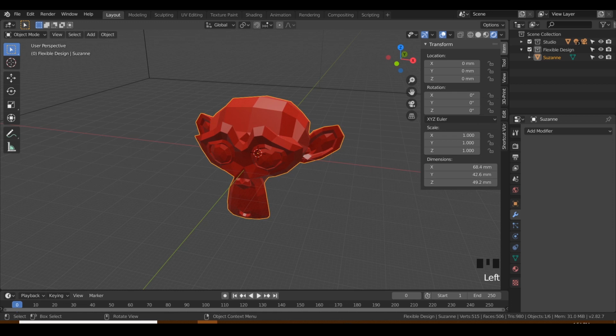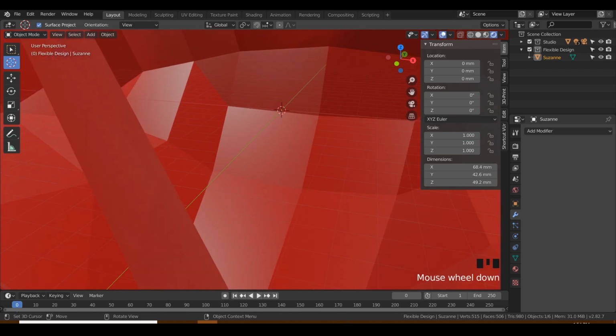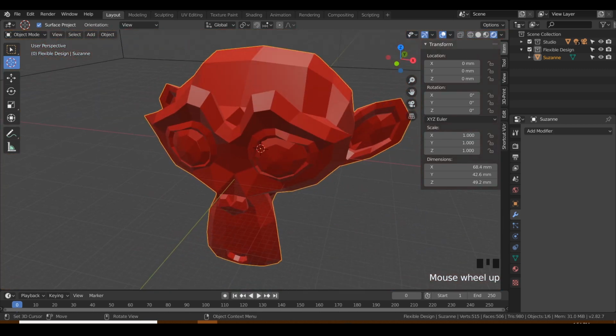In this lesson, I want to teach you about the 3D cursor. And the 3D cursor you can just turn on in your Tools panel just by hitting T and clicking on this little circle with a plus in it. And that will let you manipulate this little widget here. It's kind of hard to see, but it's this guy right here in the middle. Right now, it's just set at default 000, but you can move this anywhere you want.